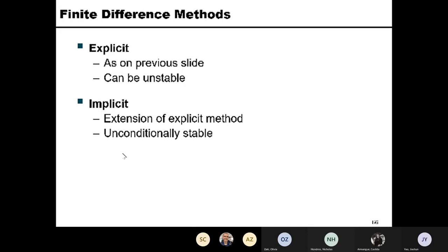The implicit method is actually unconditionally stable, because basically just like inversion, you always try to fit a solution to the current equation, right? It's always stable, so unconditionally stable, right? So this is the difference. However, because with implicit you need to solve an equation. For a single equation, fine, but for a huge system, maybe 300,000 unknown variables, that means you need to solve a huge linear system of equations, right? So the computation is more expensive, right? That's the difference.